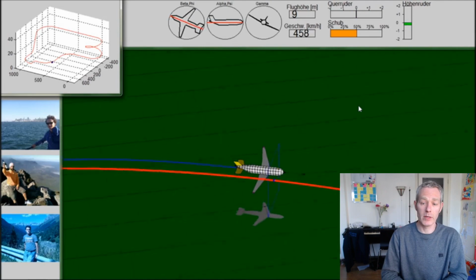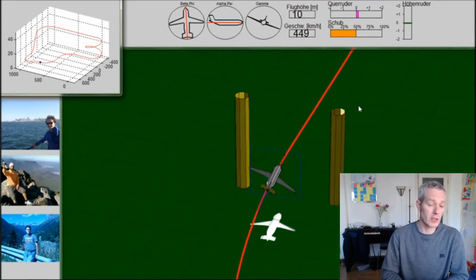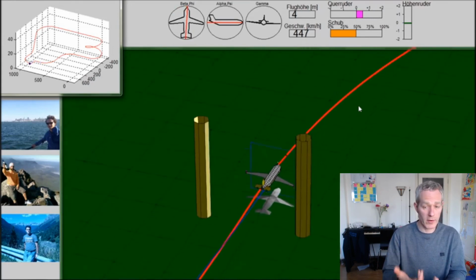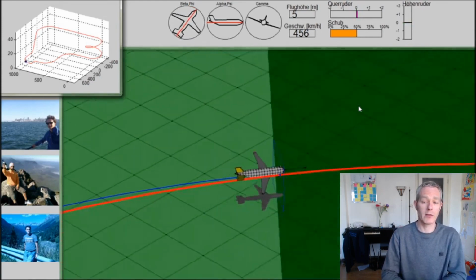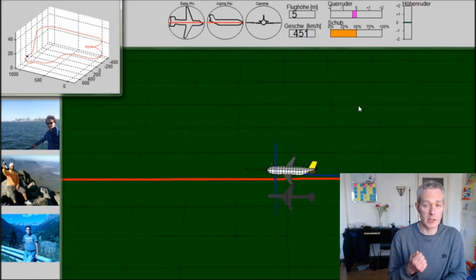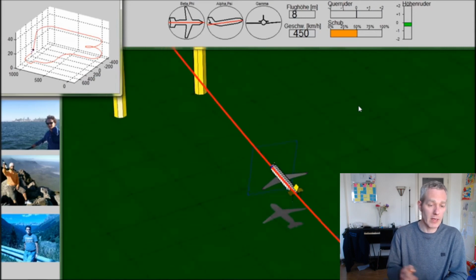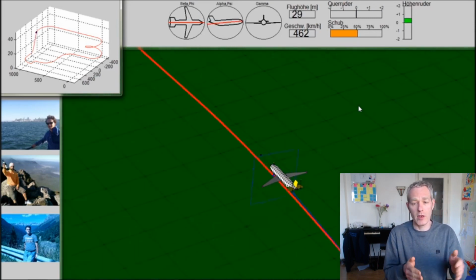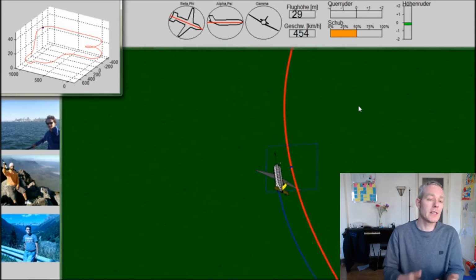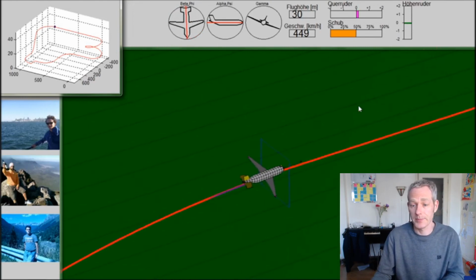And you will see it will not follow the line perfectly, because controllers have certain limitations, and you also want to keep in mind that you don't want to control too fast, like in the car example, and here as well. So there will be a bit of a delay in response, or a response which is too little, and there'll be some overshoot where it tries to find its trajectory, but will overshoot in altitude and in heading a bit. But these are properties of control systems that we will just have to accept.